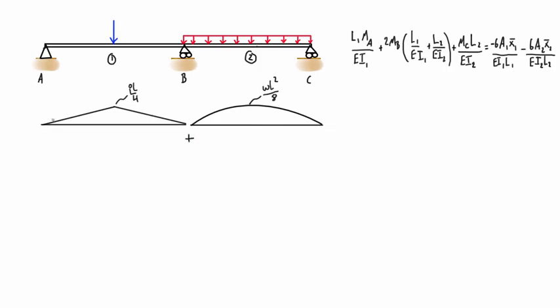So anyways, moving on with the principle of superposition. We start out with the bending moment diagrams as if they were simply supported, carrying the moments basically caused by the applied loads. Then what we want to add in is the moments caused by the supports, because we need to include the end moments here if they exist, because the actual moments on the actual bending moment diagram may not be 0 at all of these points. To account for any non-zero moments at A or C, we draw them on like this.